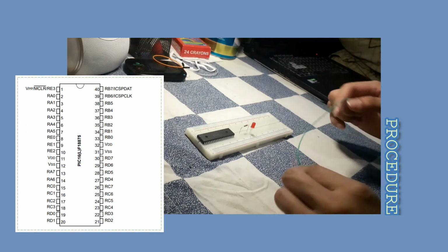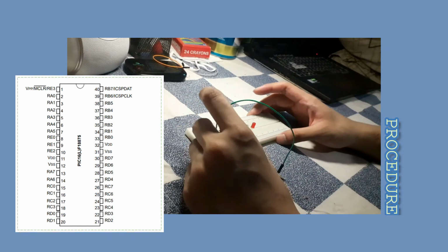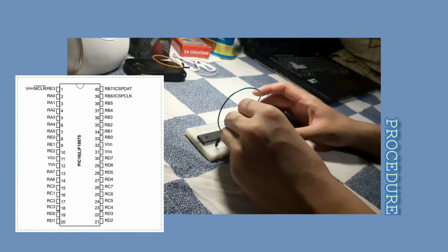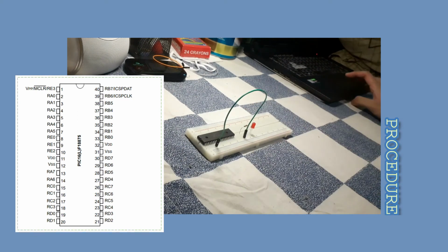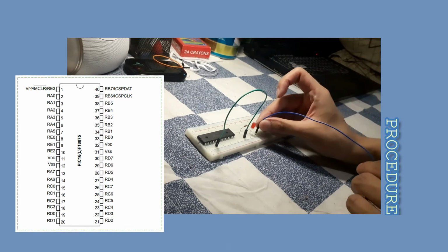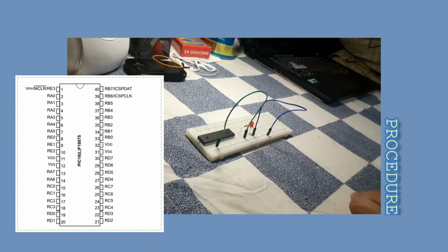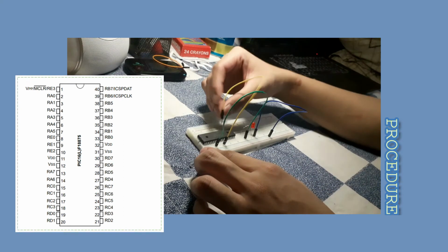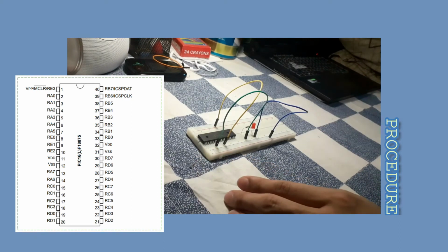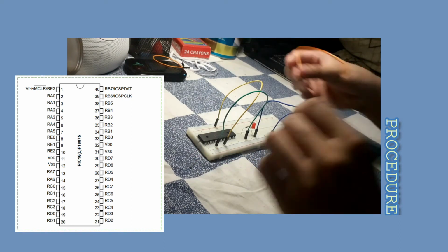Again, let us connect first your pin 6 to your output. We used pin 6 because it is labeled as RA4 from the schematic of the integrated circuit. Remember that we used RA4 during our programming method. We used port A4 for the integrated circuit as the output. And then place the VDD on the positive side, which is pin 11 and pin 32.